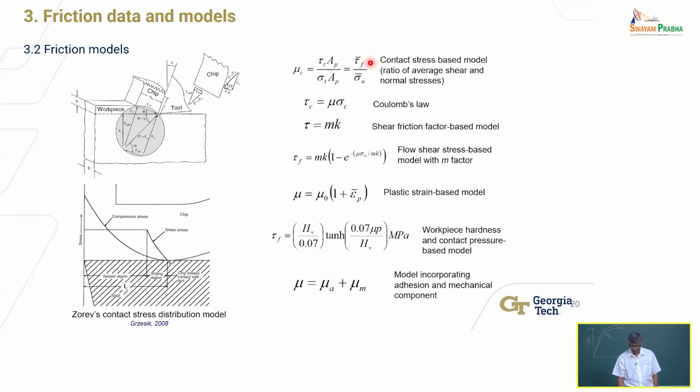This is analogous to, so this is like your Coulomb's law in some sense, okay? That's what this is, effectively. But this friction stress, like frictional tangential force divided by normal force, this is in terms of stresses, the same thing, okay? Except we know that the tangential stress and frictional stress, normal stress change as a function of strain rate and temperature. So it's more complicated. There are more sophisticated models like this, okay? You can describe much more sophisticated models that people have tried and used, okay?